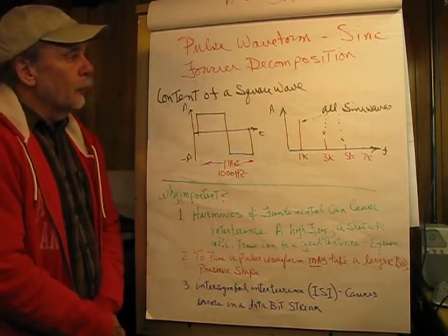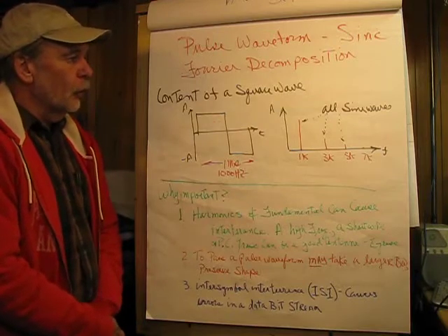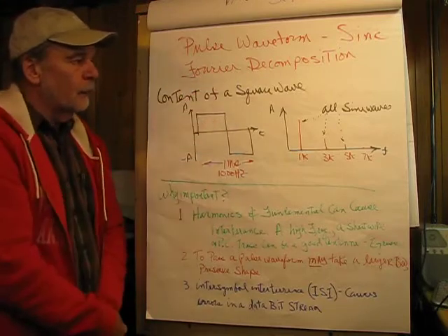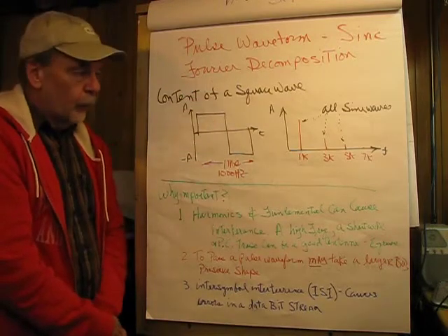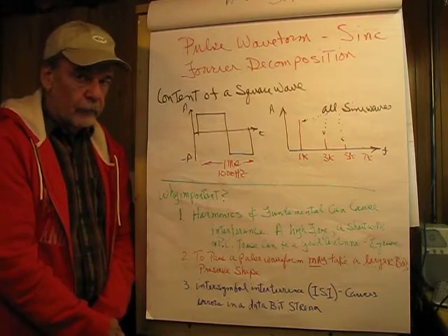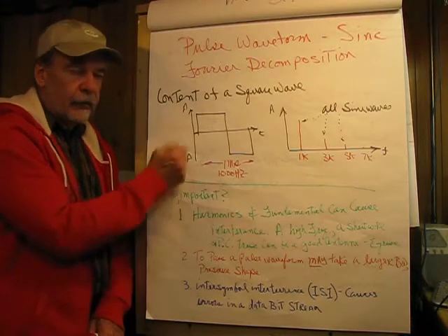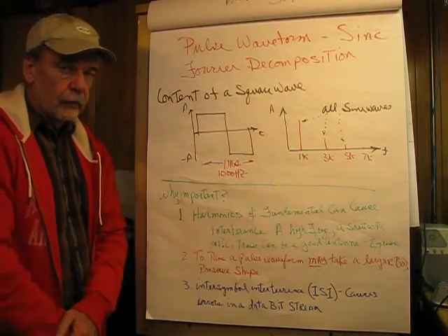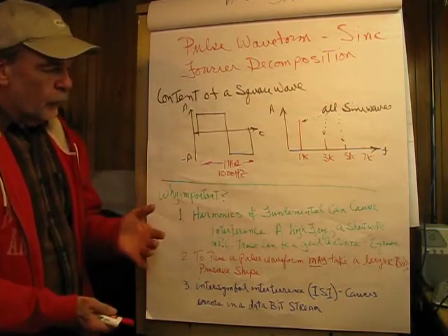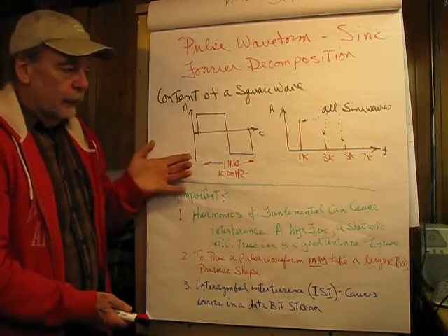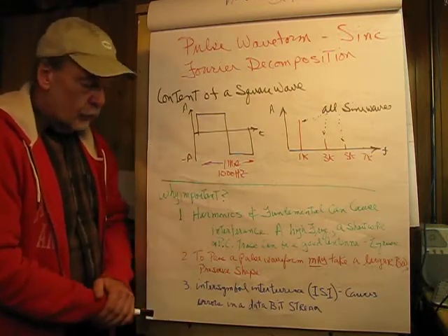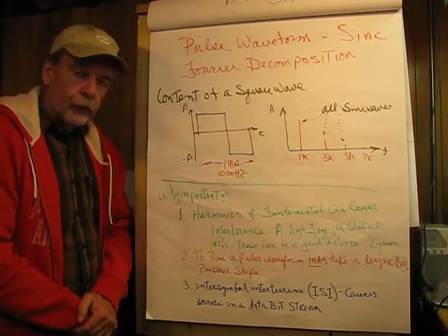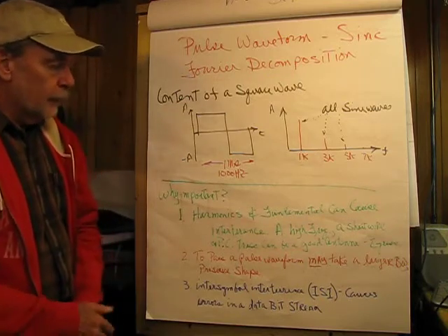So what we're going to do first off is take a look at a square wave, and this whole technique was determined by a mathematician named Fourier. We're not building square waves with sine waves, but what we are doing is analyzing them, and every time you see a spectral spike, it is a sine wave. For these common waveforms, fortunately, a lot of fairly complicated math is decomposed into relatively simple formulas that we can use to determine the frequency and the amplitude of harmonics.